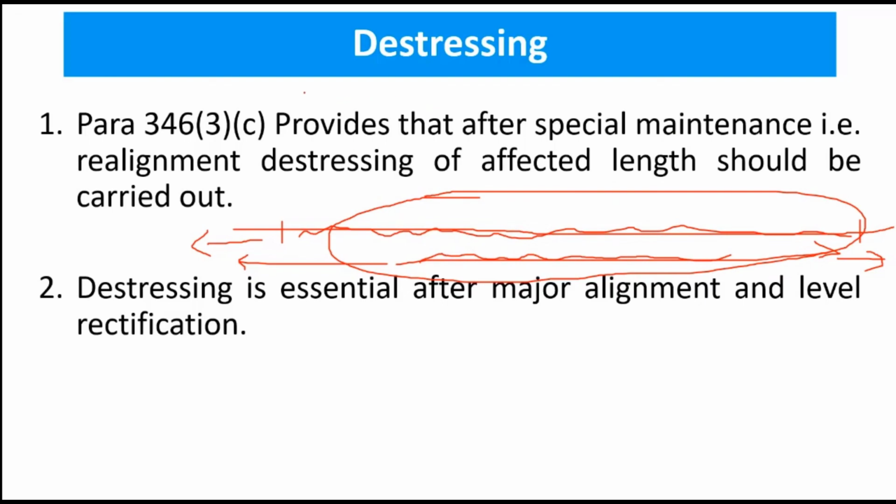We follow this tamping by the survey trolley method or the survey by total station method, and then do the de-stressing by tensor, and we get a good track.